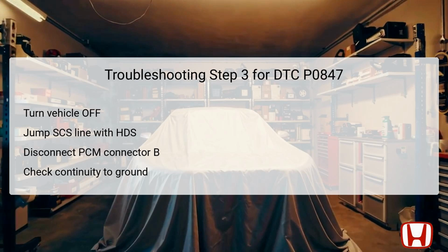the wiring. First, ensure the vehicle is turned off and in lock mode. Subsequently, jump the SCS line using the Honda Diagnostic System, HDS, allowing diagnostic procedures to initiate while waiting for a minimum of 1 minute. Once this action is complete, the next task is to disconnect PCM connector B, particularly the